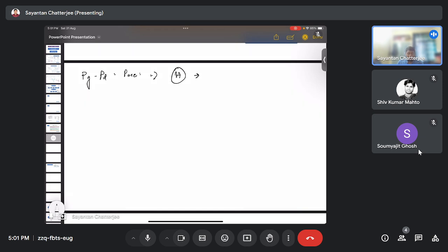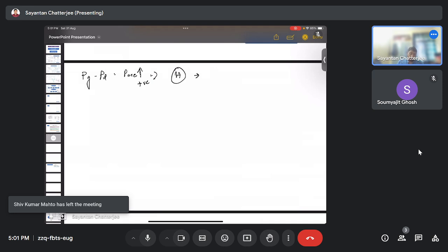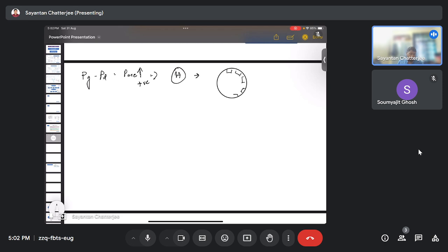If this accelerating power is positive, that means generation is more, and the rotor would try to accelerate. But all these machines are synchronous machines, so the rotor can't accelerate freely, because we have distributed field windings in place, and we have the rotor inside. Here the rotor also has field windings. It's considered as the cylindrical rotor case for the synchronous machine.